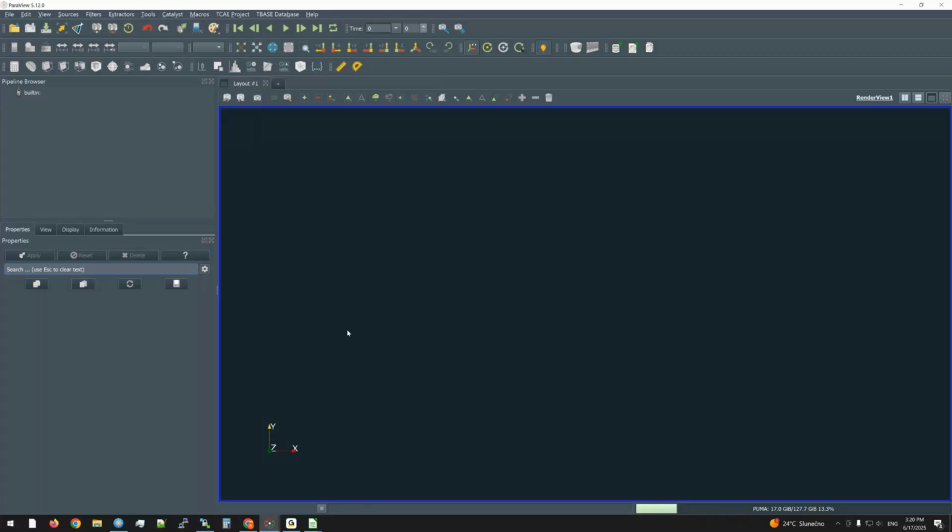You can create a script which you can run then automatically or from the console to create all the stuff you have defined, or when you are more familiar with the Python code, because the interface behind it is so-called ParaView Python, in which you can script all what we have basically done by clicking. And there is a nice tool which is called the tracing.